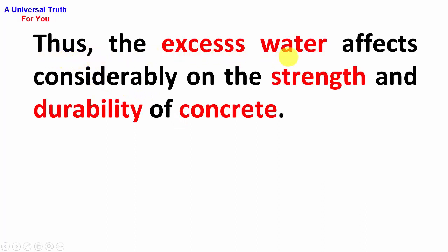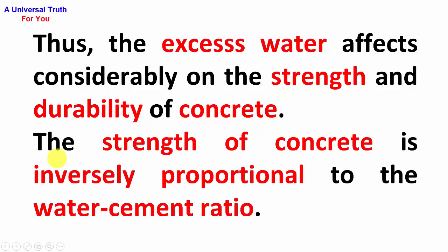Thus the excess water affects considerably the strength and durability of concrete. The strength of concrete is inversely proportional to the water cement ratio.